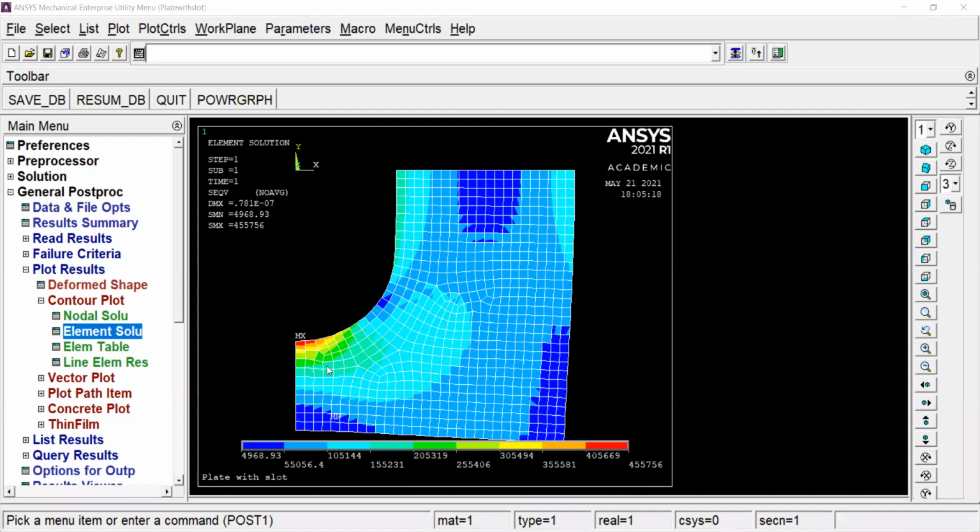Crack propagation. Just look into that. You might be able to include some information there to explain why our maximum stress is here. Also note that the maximum stress point is occurring at a plane that is perpendicular to the direction of the force. Also quite an important observation.